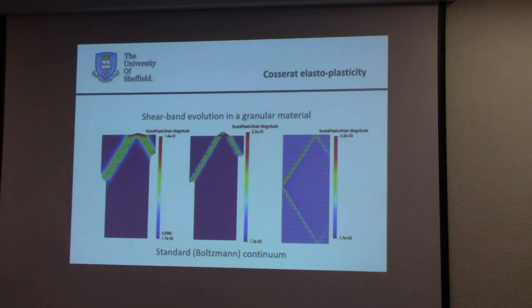Now, the important thing is that in elastoplastic computations you get mesh independence. Well, this is an example of calculations with elastoplasticity. In this case, I have used a plastic potential function which is different from the yield function, not even including softening, no large deformations, but already difference between having a different yield function from plastic potential is sufficient to lose ellipticity, which means it's sufficient to get mesh dependence without even material softening. And then you get this.